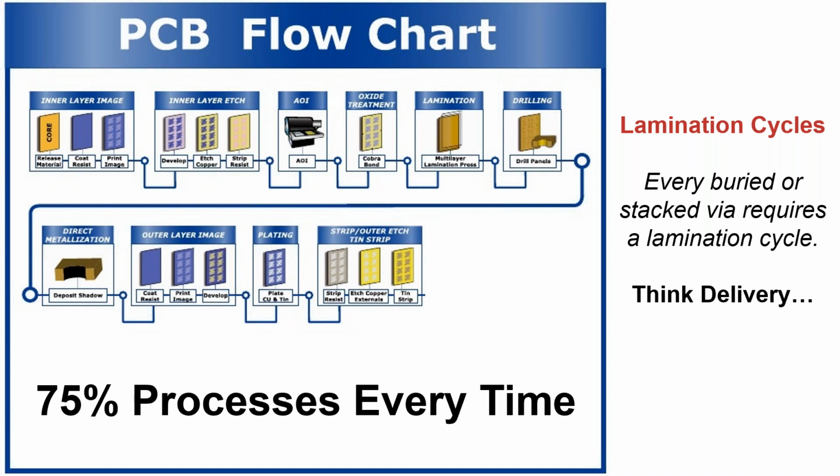And that's what adds the cost to the printed circuit board, because you're basically running the board almost 3/4 of the way through, and then you've got to go back and do it again. And along with that, when you're looking at it from a quick turn perspective, what you don't see in here are any of the bake or pre-bake processes that are required.